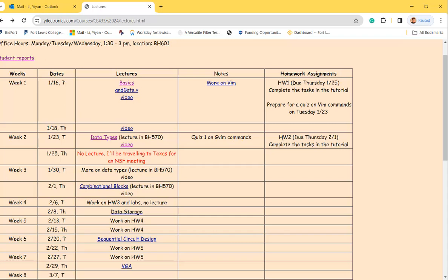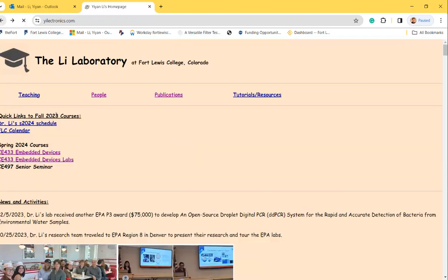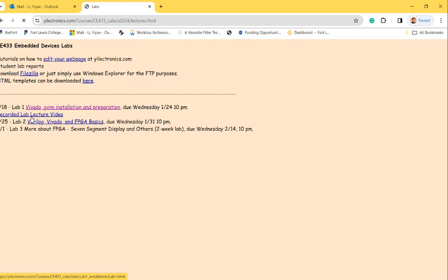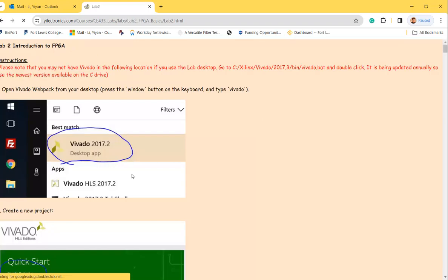When we were doing the program memory thing, I don't totally remember what it was called, where you have to switch the jumper and then it holds the program on the board. You have to select the device in Vivado. The device that was listed didn't work for me, but it said devices don't match, try this one instead. I tried that one, it was completely different and it worked. Let's take a look at it. It might have been the first lab, or no, it's the second lab.